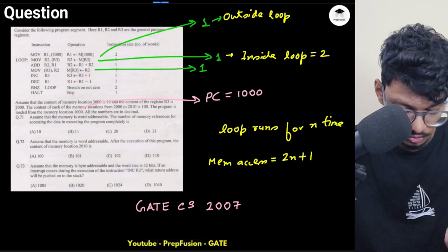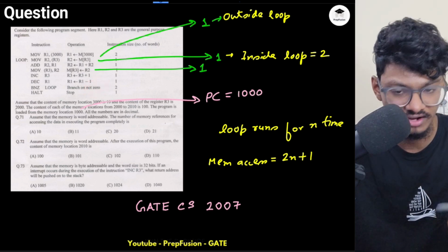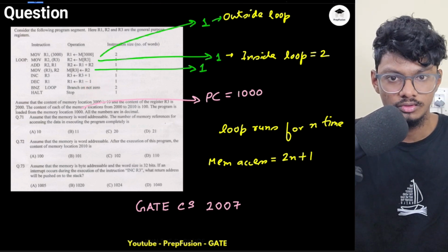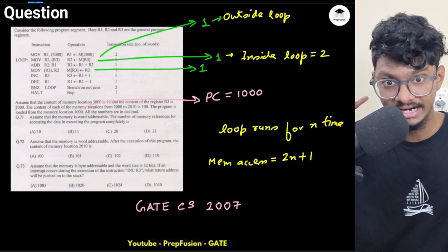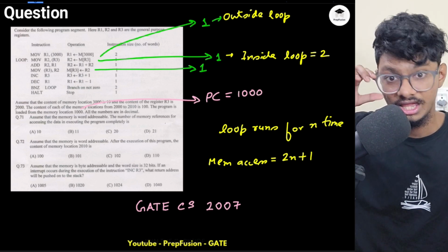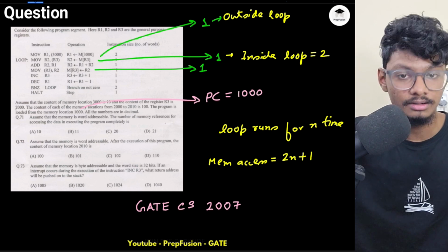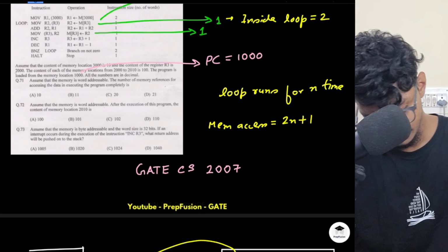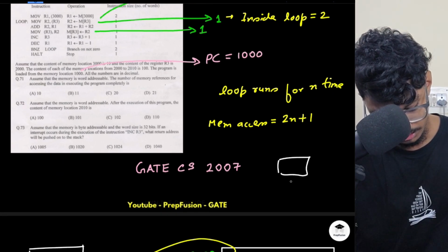This means branch not 0. It checks the 0 flag. There is a flag in the CPU that records whether the previous arithmetic operation that we did was 0 or not. There is a bit for the 0 flag, right? Okay, this is the 0 flag.